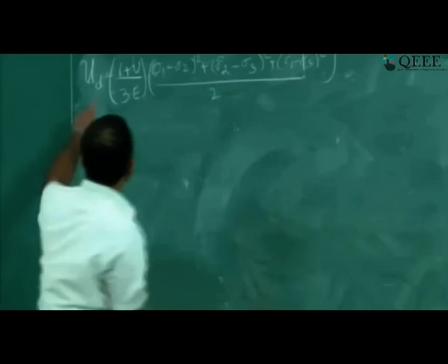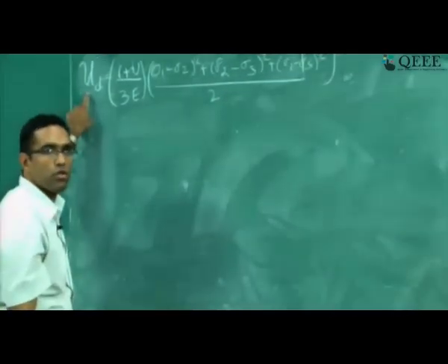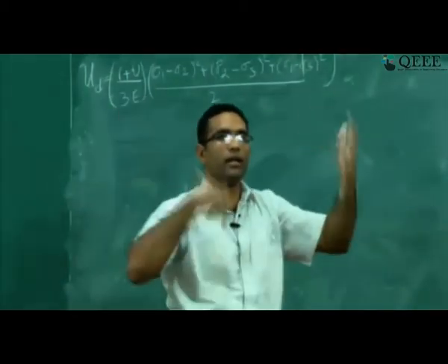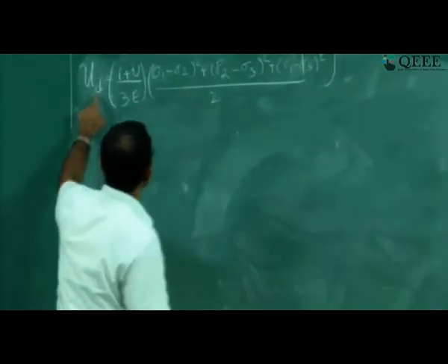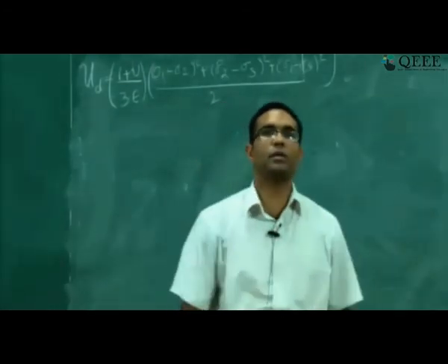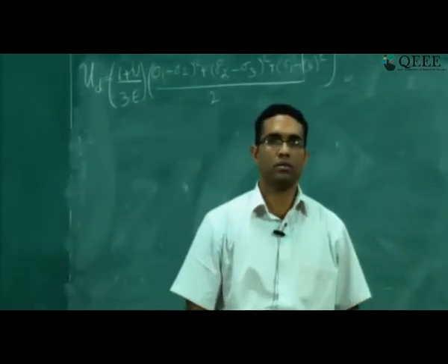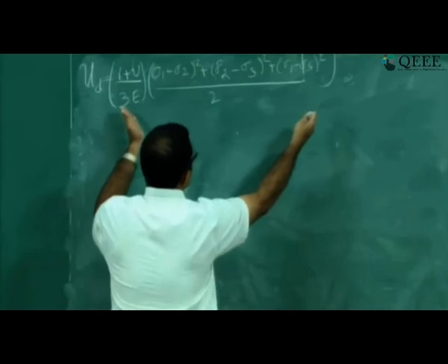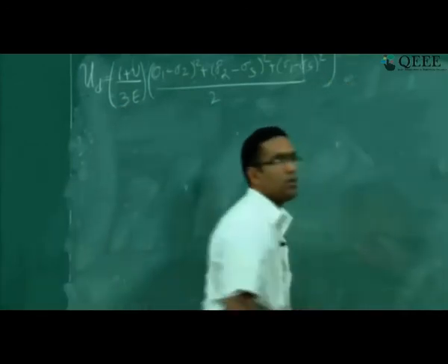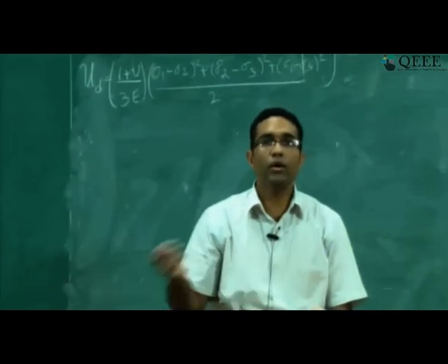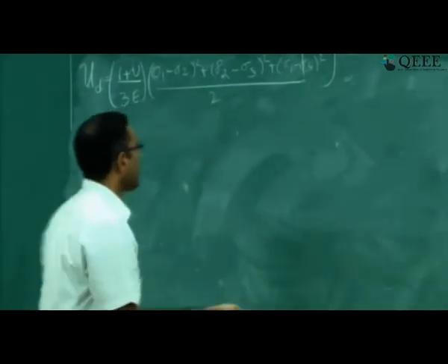This is the strain energy density stored in the material. So a material is arbitrarily loaded, right? At every point in the domain you can calculate this number. Now how will you know whether that particular point is failing or not? You need some right hand side, right? You need to say that the distortion strain energy density stored at that particular point was equal to some number because of which I claim that particular point has failed. So how will you find out that right hand side? That's what I am going to talk about.